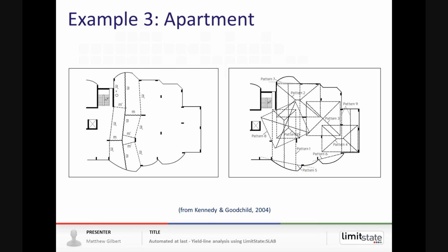Because obviously if you're doing a yield line analysis, you've got to postulate a failure mechanism that is as close to what would actually be in existence as possible. But in order to take account of the uncertainty in this, the design guide did suggest that a margin of safety, in this case of 15%, was applied to account for this potentially inaccurate mechanism.